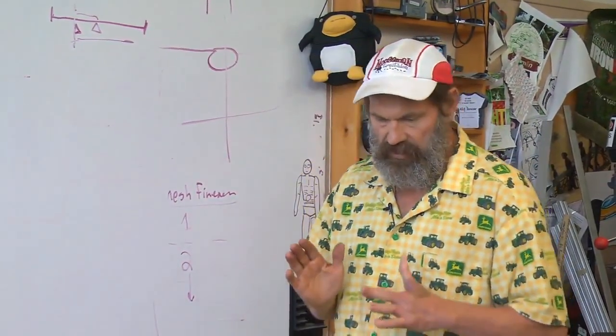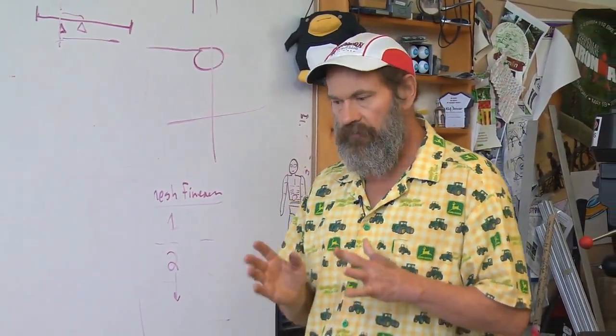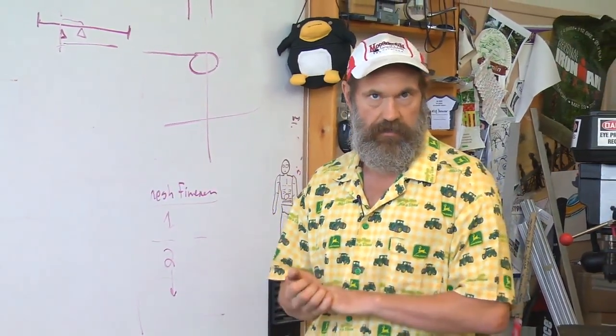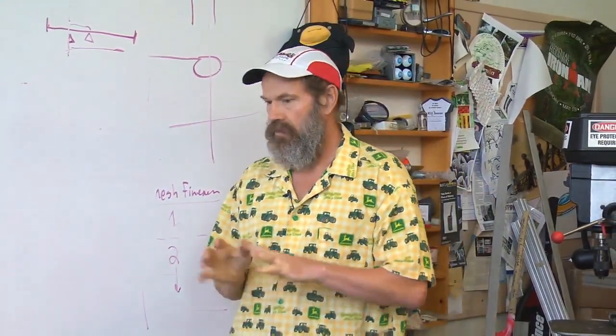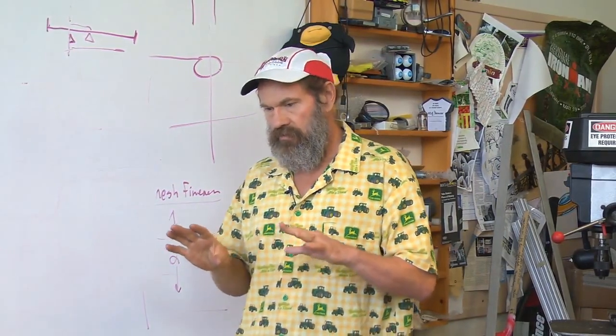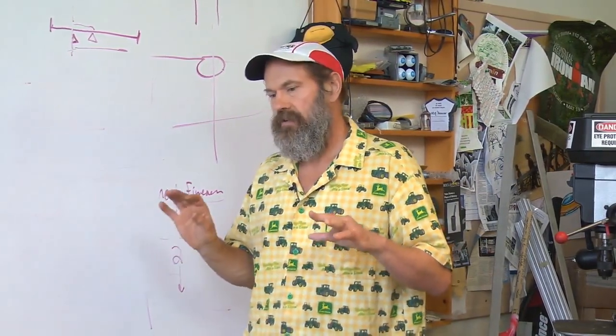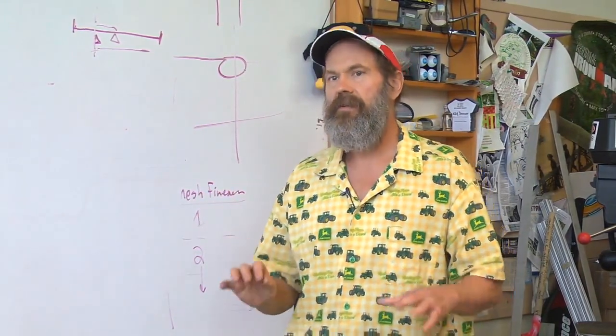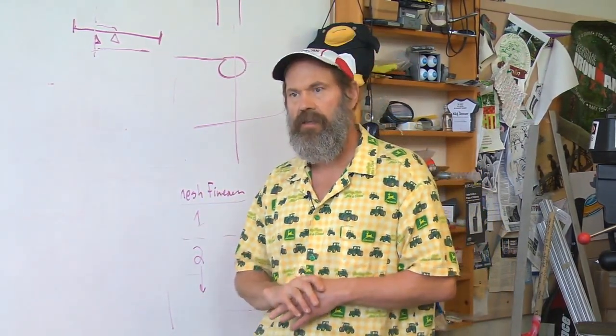Remember, whenever you have a sudden change in something, it's often good to remove material and put in a nice gentle fillet to prevent that stress concentration. Okay? Now, let's go to the remaining topics of how we minimize the weight while maximizing stiffness and strength.